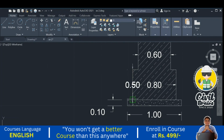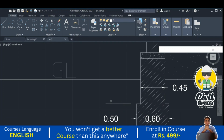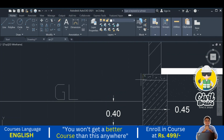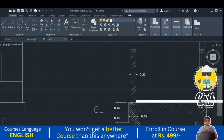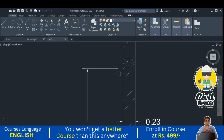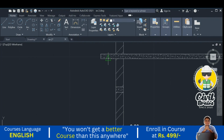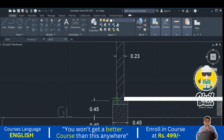Okay, so now depth, depth of the PCC, depth of the first step, depth of the second step, depth of the plinth below ground level, depth of the plinth above ground level, next lintel, no need to show the lintel, directly we'll show the slab bottom.